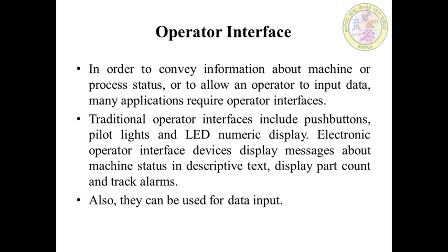And coming to the operator interface, in order to convey information about machine or process status, or to allow an operator to input data, many applications require operator interfaces. The traditional operator interface includes push buttons, pilot lights and LED numeric displays, and electronic operator interface devices display messages about the machine status in descriptive text, display part count and track alarms. They can be used for data input.